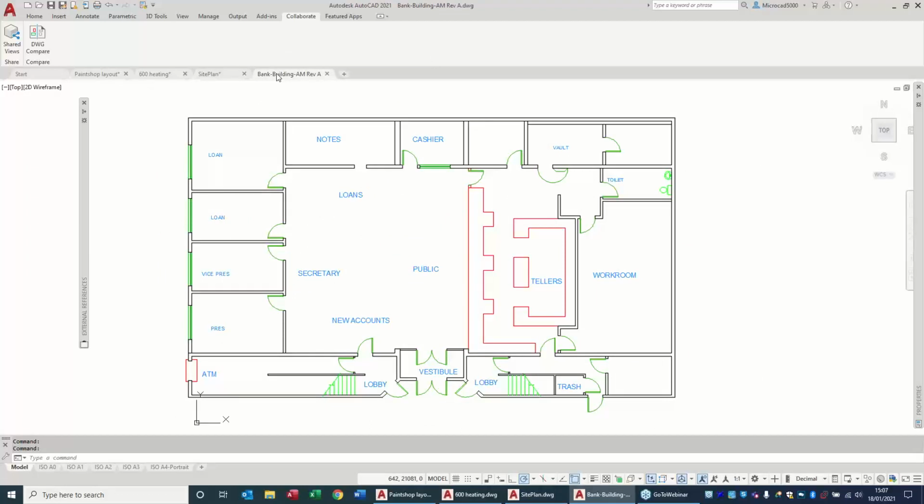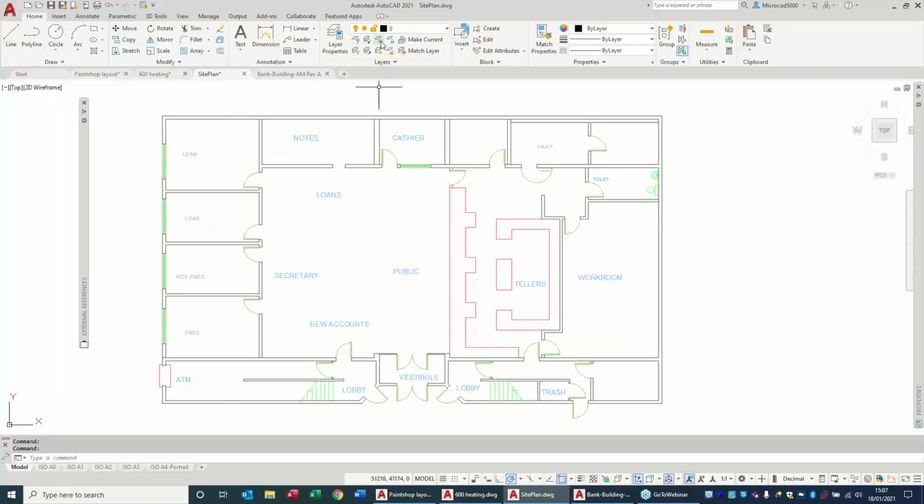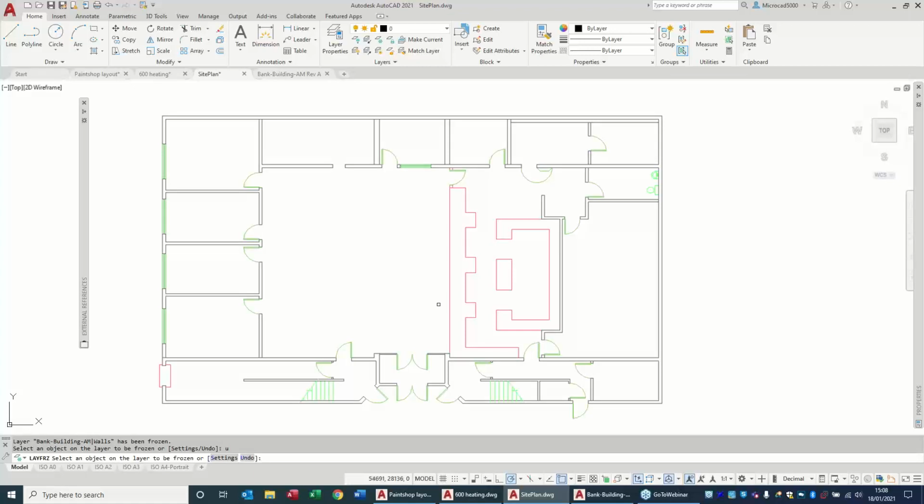Now, there is a variable that controls the layers. Because in the site plan drawing, you might want to turn off, say, the doors or the text or something like that. So in the Home tab, I'm on layer 0. If I say freeze the text and freeze the doors, oops, okay, not a very good drawing, and freeze the furniture, that disappears. Now, if I save my file, when I reopen it, I would hope that those layers are still in that particular state.